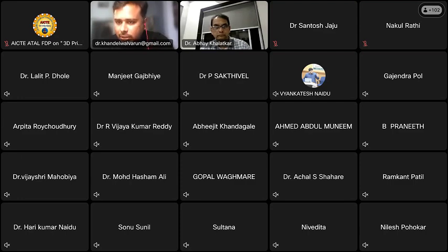Kumar sir is asking which mechanical test and characterization is to be done before fixing a new implant. We cannot place any implant before regulatory clearance. If we talk about mechanical testing, simple stress strain analysis needs to be done under both static as well as cyclic nature of forces. For a dental implant, how many cycles of force it takes before it develops a fracture line needs to be evaluated. If any company is selling an implant which is ready to go into the body, it has already been tested for that. But both the static as well as the dynamic forces for stress strain analysis need to be done for every kind of implant.